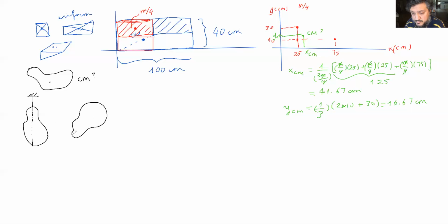And the original line was going through like this, but now you're hanging it over here from that point. Same idea. So the center of mass will be vertically somewhere below it, but you know it can also be on this line. So the only option is where they intersect. So that's an experimental determination of the center of mass.